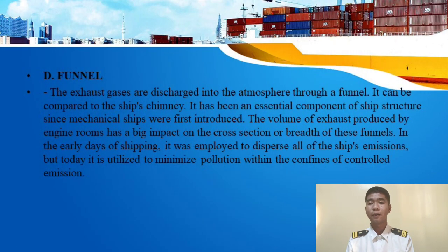The next one, funnel. The exhaust gases are discharged into the atmosphere through a funnel. It can be compared to the ship's chimney. It has been an essential component of ship structure since mechanical ships were first introduced. The volume of exhaust produced by engine rooms has a big impact on the cross-section or breadth of this funnel. In the early days of shipping, it was employed to disperse all of the ship's emissions, but today it is utilized to minimize pollution within the confines of controlled emission.